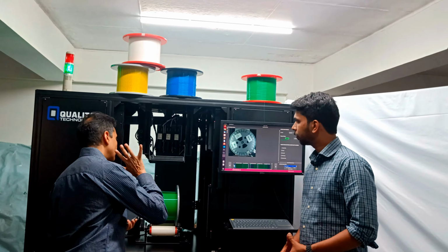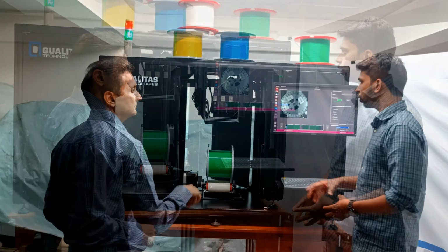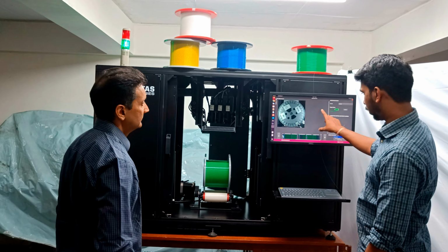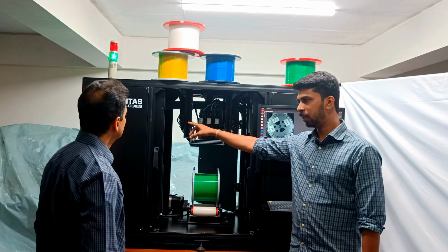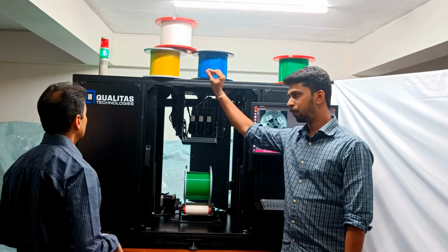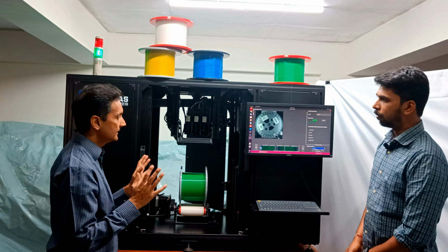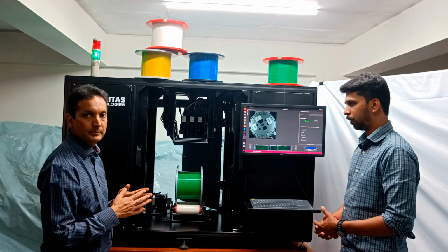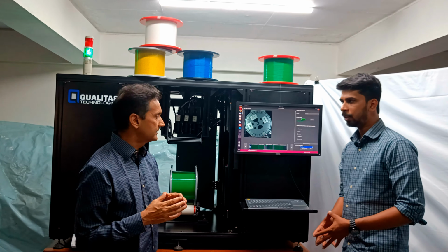And then the output of the PC, what happens? So if a defect is found, what happens? So once the inferencing UI on the PC gives us an output that it is defective, the output is given to the PLC. So from the PLC, there is a visual output. It flashes red, along with a beep. And then the operator knows that this is a defective sample, and he can set it aside for rework.